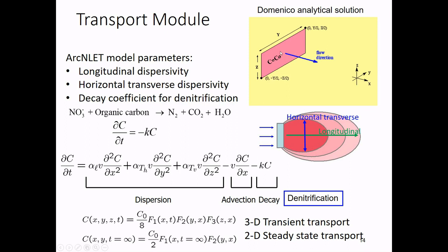So imagine this is a plane producing nitrogen continuously at a concentration of C0, and then this concentration or mass is going to move with water, with the groundwater flow, and also it disperses out. So this is an illustration of what it means to disperse out, because it's not a pencil flow. The contaminant will not move along a line. Instead, they're going to spread out because this is porous media. You have a mechanism called dispersion here, right?